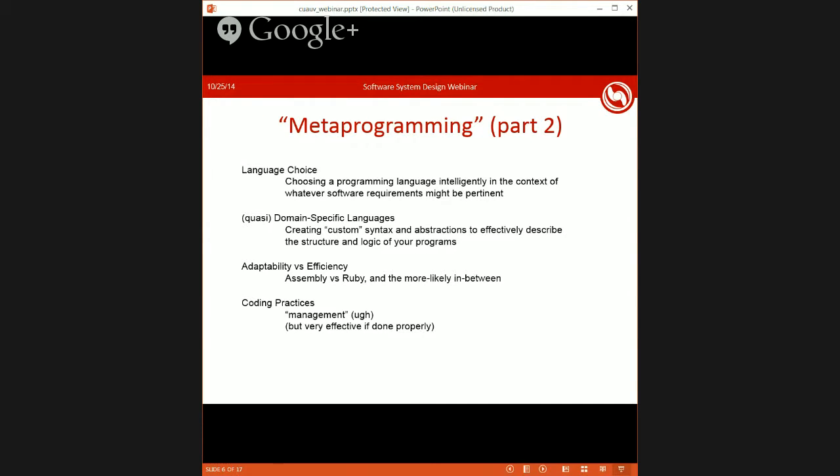If you're writing a mission system, you don't want to deal with the low level of how to run the motors. You just want to deal with what to do based on this set of stimuli, based on where this object is. I want the sub to do this, to go to this place, to run this action, run this actuator. And you want the parts of your code base to deal with how the sub does that, say how it translates velocity desires into motor values, or how it translates vision inputs into object coordinates to be elsewhere,